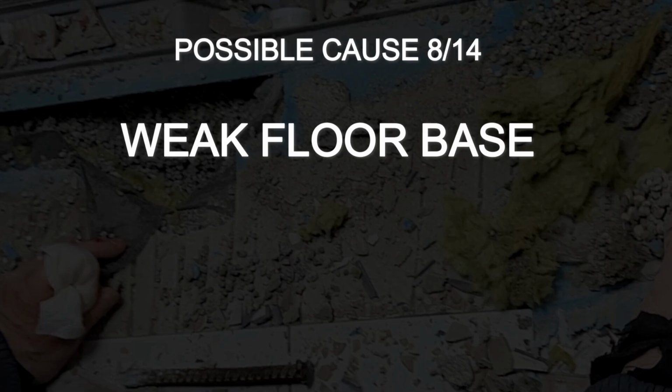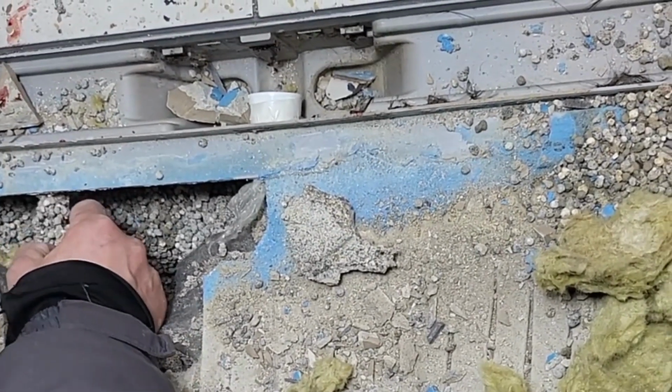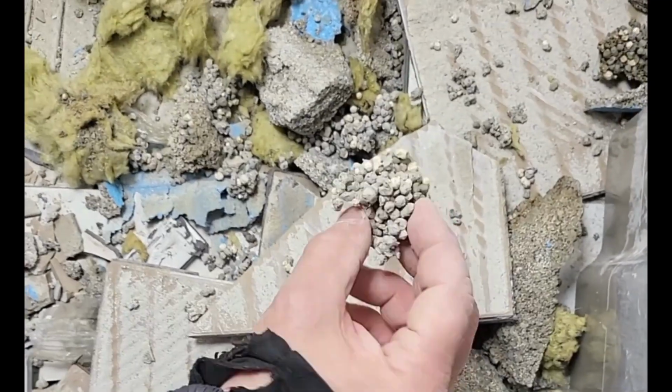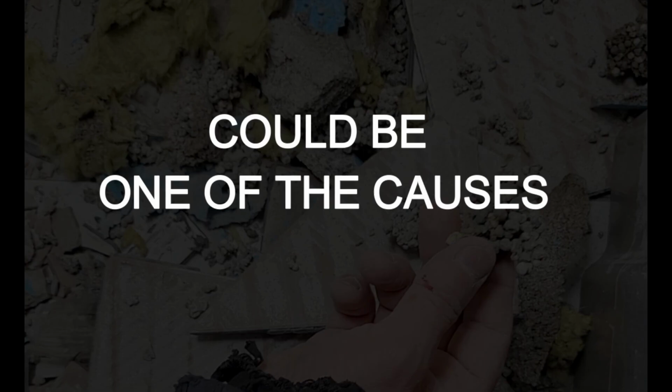The mixture of polystyrene beads and binders used for the floor base crumbled easily in the hands. We did not perform a separate strength test, but such a layer must be strong enough to support the flooring above it. If it settles unevenly, the tile grout may crack. This could have already explained some of the cracks, but we still didn't know where exactly the water had breached